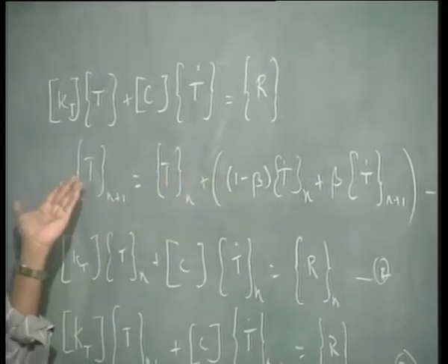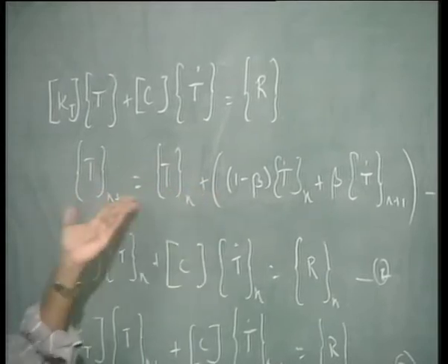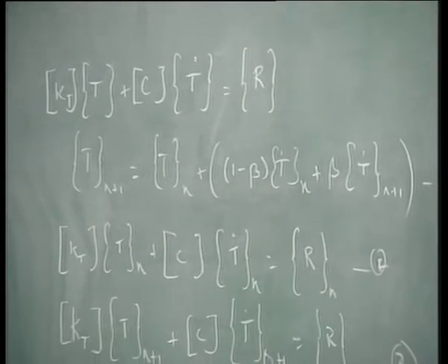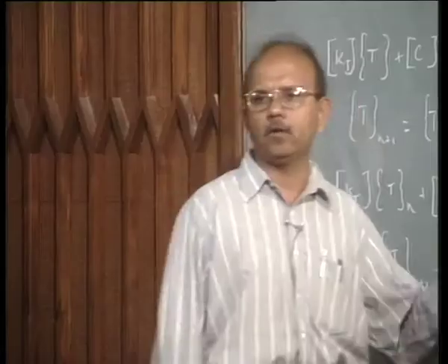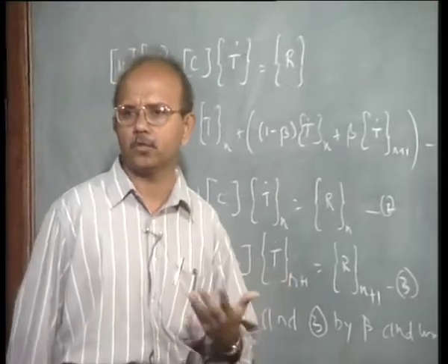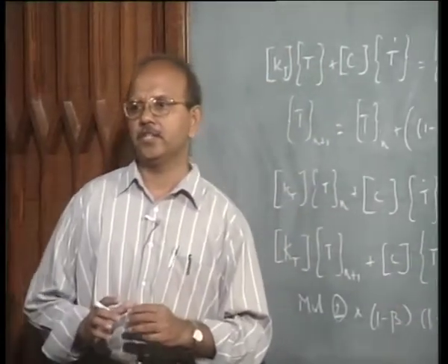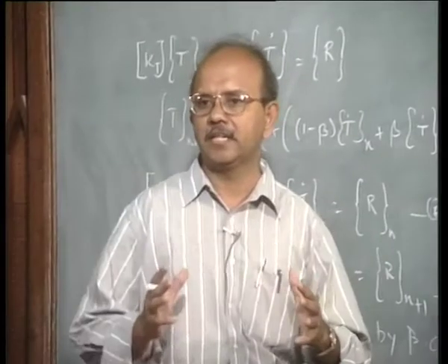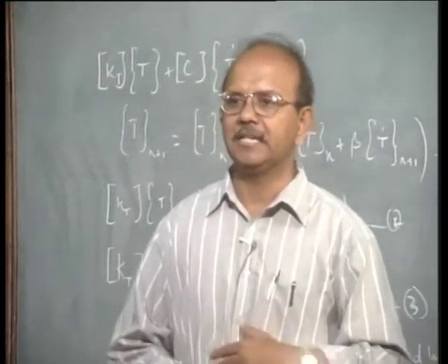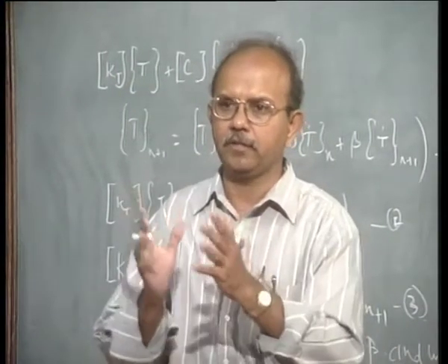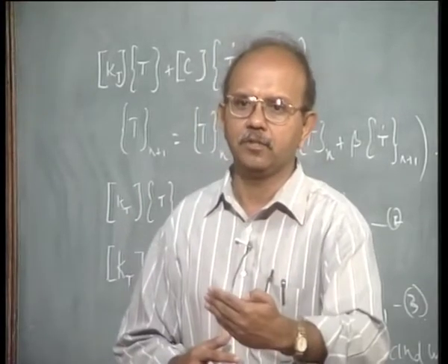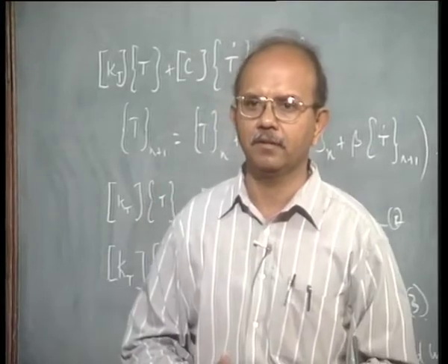People who are familiar with the finite difference approach for numerical analysis would immediately realize that what we are looking at is similar to many of the schemes you have seen. Maybe people would have called this the midpoint rule or trapezoidal rule and so on. So, in other words, you can summarize at this point that you had discretized and used finite element analysis in space in 2D or 3D, and you are marching ahead in time using a finite difference scheme, right.